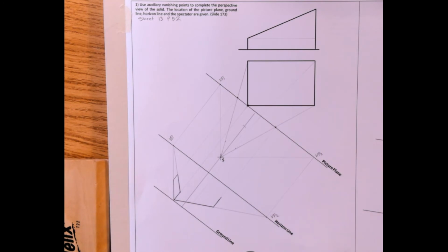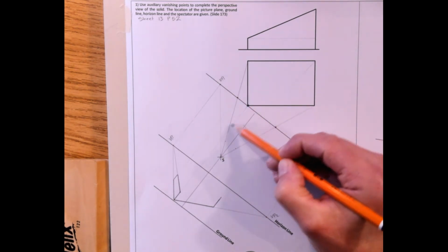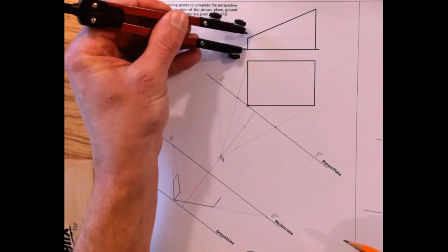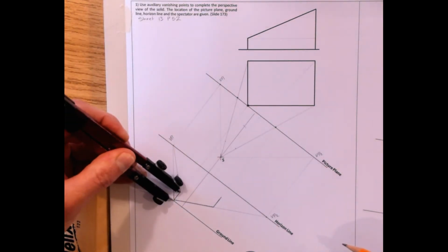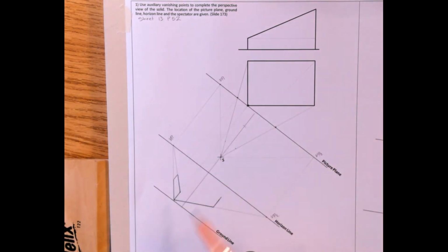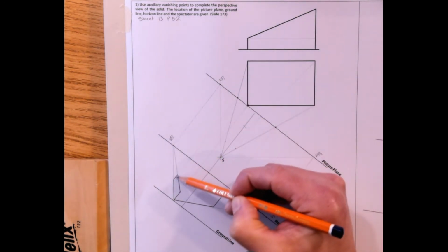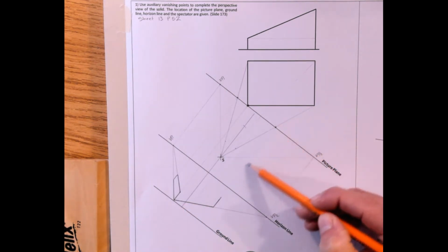The setup of the question then is the same as we always would. Our corner touches the picture plane, so that's where we start. We project our corner into plan. We measure the height of it, which is taken from our elevation. So we can measure that height, step it off, and we vanish our 2 lines in the direction of vanishing point 1. Back corner is brought back to hit the picture plane and down to get our back edge. So that's our front surface drawn in. Vanish in the opposite direction here to get the bottom line, the long edge, and we basically take our corner back and down to get the long edge.